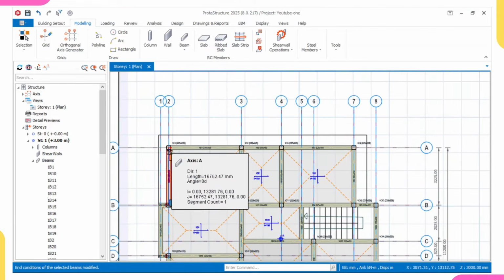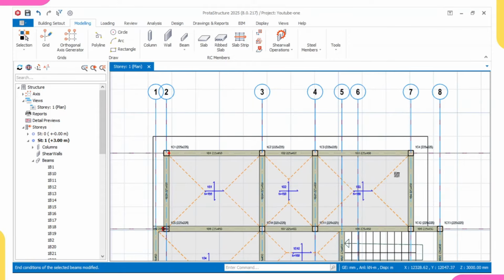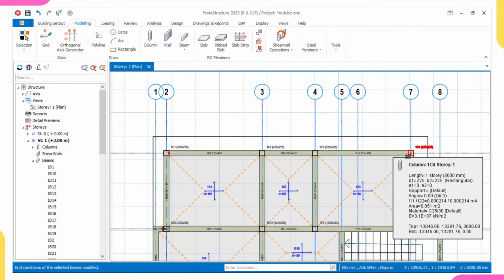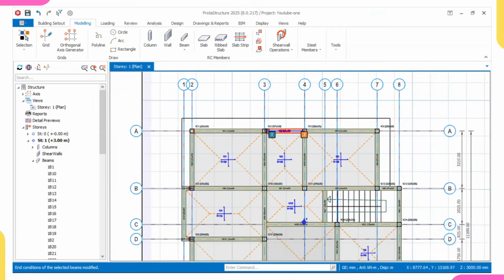So in drawing this beam now, it will be going like this. It will come here, it will go up, which is hogging moment, it will come down, go up, hogging moment, come down, then terminate here. If you can remember your university days when you were drawing bending moment diagrams, the bending moment diagram will go up, hogging moment, come down, sagging moment, go up, hogging moment, come down, sagging moment, then terminate at zero. I hope and I believe that I've been able to do justice today.